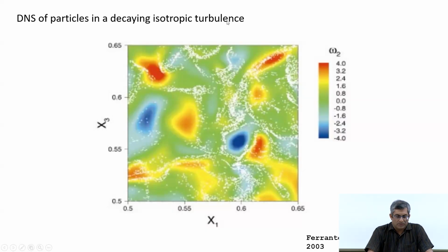Okay. So, in numerical simulations of say homogeneous isotropic turbulence, to sustain turbulence itself, an extra term is added in the Navier-Stokes equation, that is the forcing term. This is not with particles, even without particles the turbulence has to sustain.